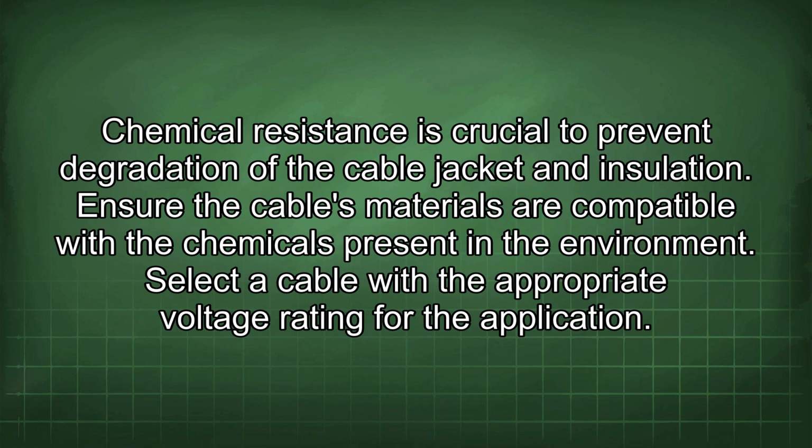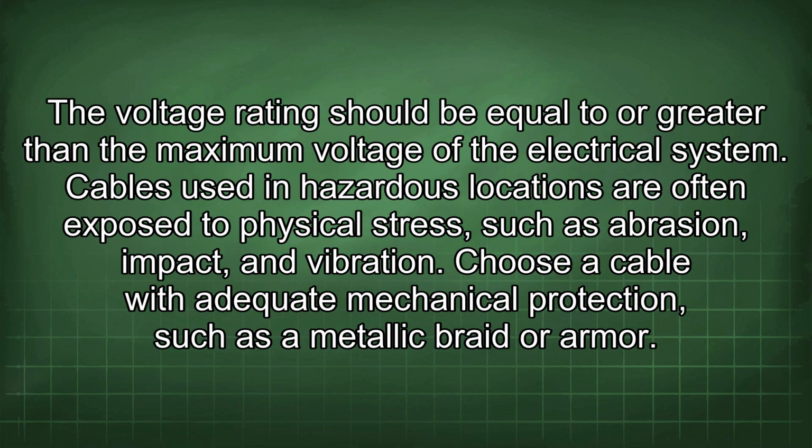Select a cable with the appropriate voltage rating for the application. The voltage rating should be equal to or greater than the maximum voltage of the electrical system. Cables used in hazardous locations are often exposed to physical stress, such as abrasion, impact, and vibration. Choose a cable with adequate mechanical protection, such as a metallic braid or armor.